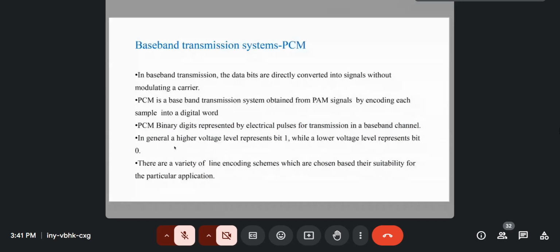And even in digital communication systems, as we are going to see later, we actually do use line encoding, because you're going to see that the modulator itself is operated by either non-return to zero, which we are going to discuss here, or return to zero, to modulate. The modulated signal will be a non-return to zero signal, which will have been produced to represent bits 0 and 1. We'll see that, but let's first of all look at what these alternatives are.